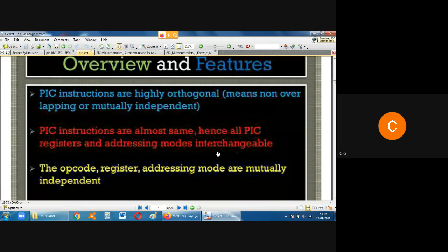In the previous case, whenever you wanted to do any operation, you had to move the content of any register to register A, and after that it would work. Okay, so in this case you can directly transfer the content to the arithmetic logic unit and the working register. You need not have an intermediate register A to receive and send the data. So earlier it was like accumulator or working register, then register A, then it goes to other units.